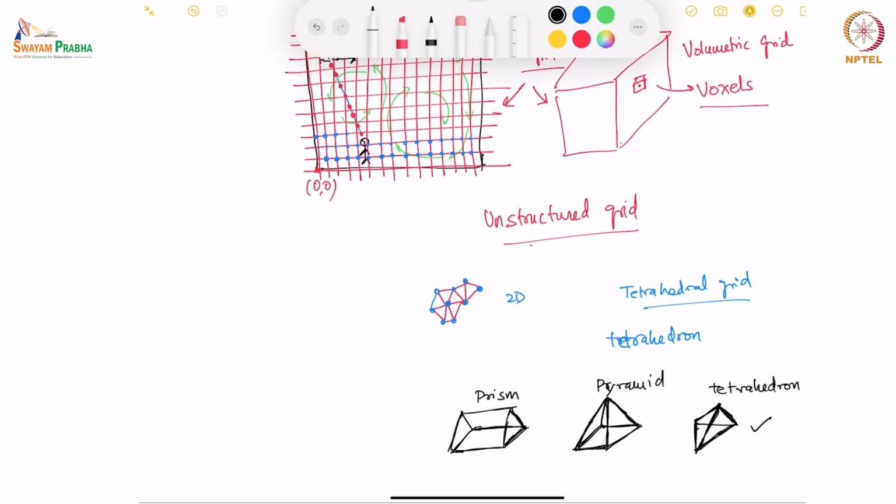We use a lot of tetrahedra in 3D to cover the entire space, and then at the vertices of these tetrahedra, you can calculate the distance value or the implicit function value. These are the points at which we had calculated. But now I want to recover my shape, so I want to calculate the level set corresponding to this implicit function. Let's see what algorithms exist for that.